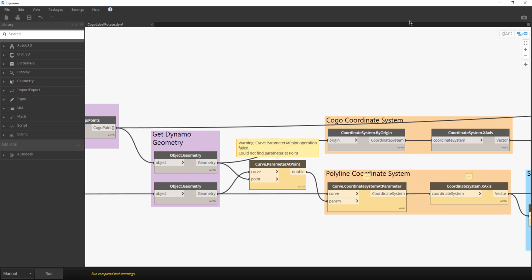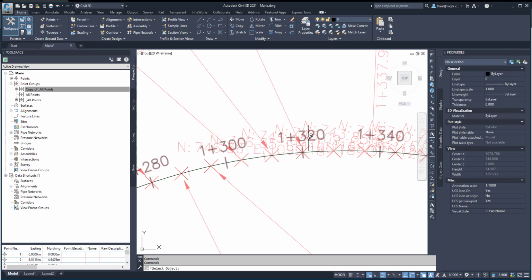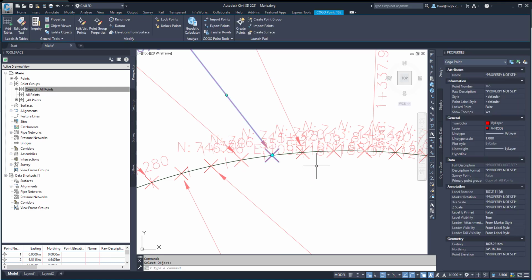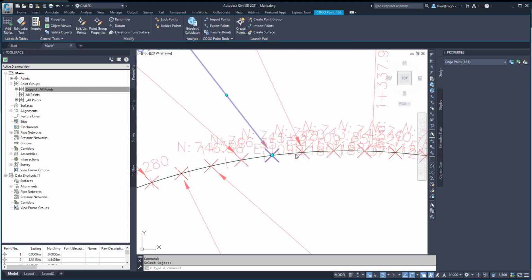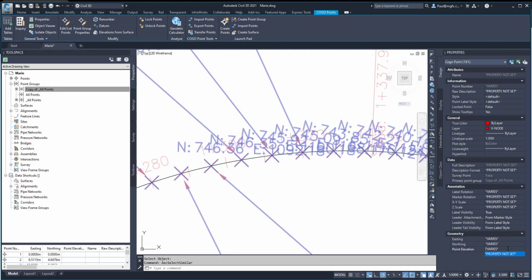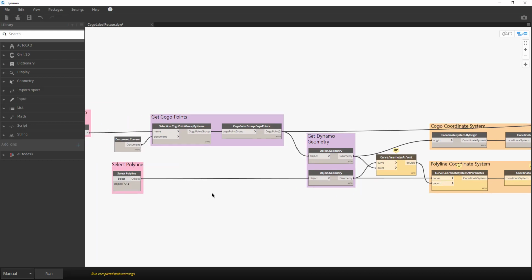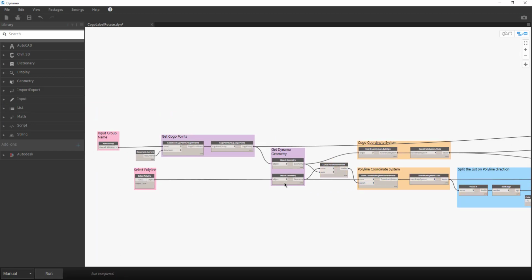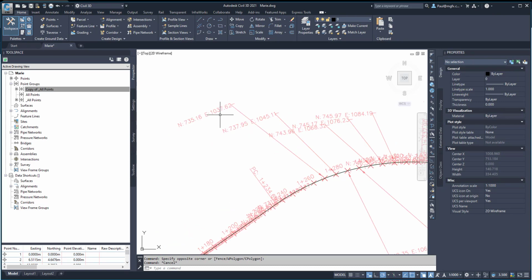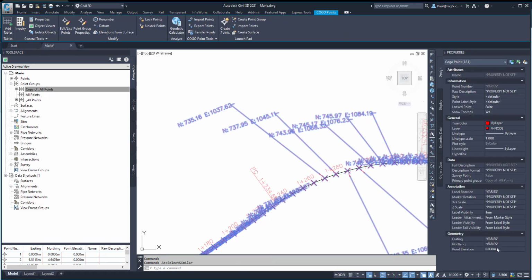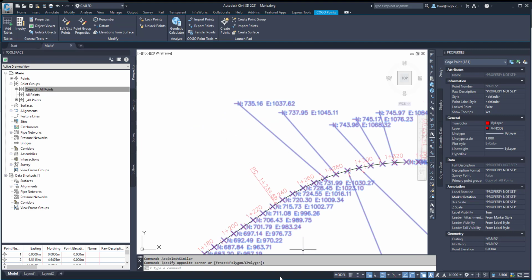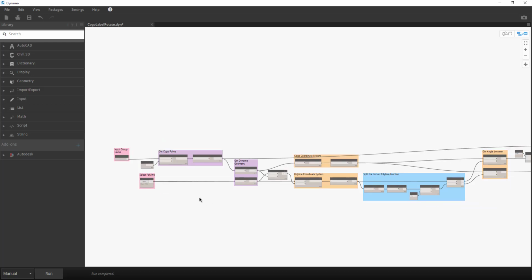And over here we can see we're getting an error. And the reason for that error was because the elevation wasn't set to 0. All right. Let's try that again this time. Just quickly select that, and the rotation is set to 0. So let's go back to our script and run that script.